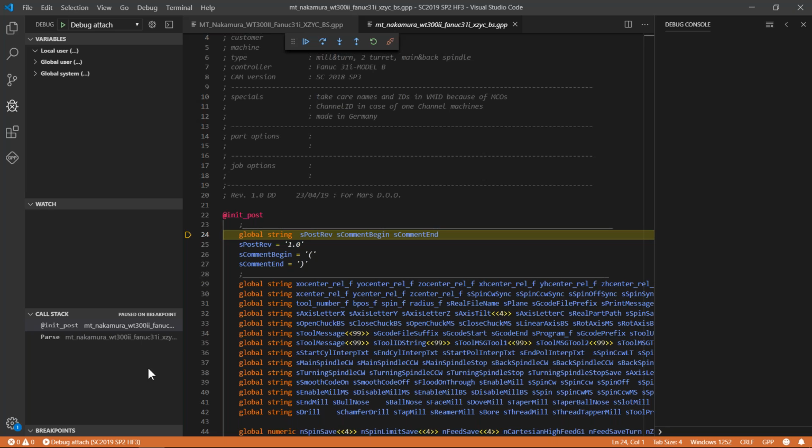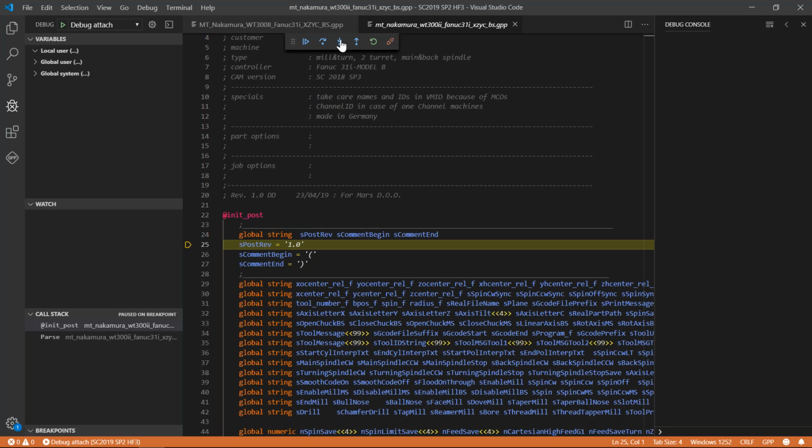So for you, the most important is to focus on the tool itself. And on the right side, you have the debug console. You will see what the debug console actually is. So I'm over here and I will not start from continue, but I will start from this step into. Usually once you get used to it, you will use the shortcuts like F10, F11, F5, and so on. But in this webinar, I will just use the mouse button. It's much better so you can actually see what I'm doing. So I will just click once on step into. What you can see is that we moved one line and we are now over here. It means this line is still not executed.